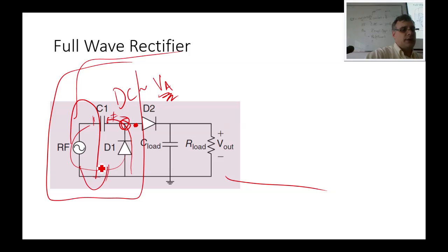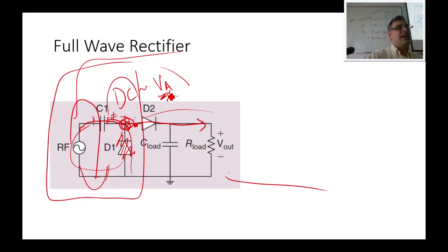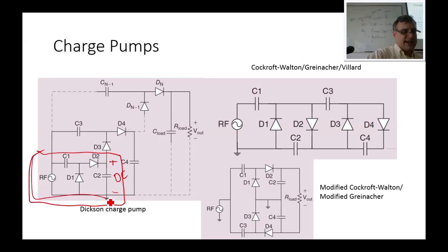When the upswing happens and you push charge over here, that charge superimposes on top of the DC value that's already there. If you got rid of this diode, it would just be a half-wave rectifier. When you put the diode in there, that rectification rides on top of what is already a rectified signal, and you get double. Now over here, I've got that exact same circuit, so I know I'm going to get a DC value that's twice, let's say I had the perfect diode with zero turn-on voltage, 2 VA, riding right there.